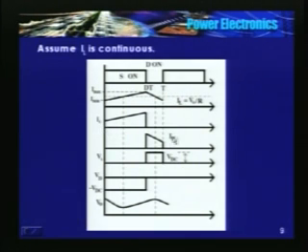So, okay, the diode should turn off at this point. Immediately I am turning on the switch here. So, this value of current the switch should carry immediately, and that current will flow through the switch itself and increases linearly, and at this point it is being switched off. Current instantaneously becomes 0.